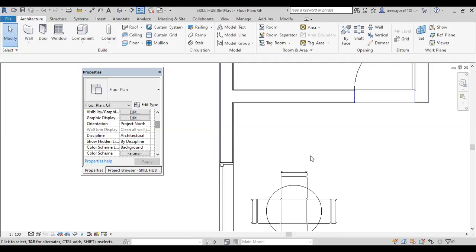If you are creating a ceiling plan, the cut plane comes under the view range. Then you change the height of the view range, and automatically the object will be visible. That is because the cutting plane is not under that level, which is why we can't see it. Later you change the cut plane, and automatically this cut plane level difference will be shown on our screen.